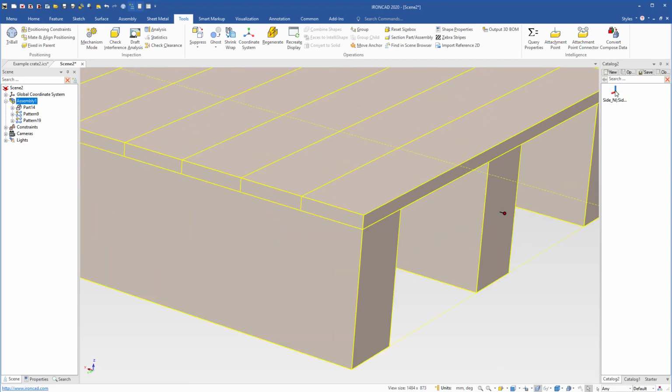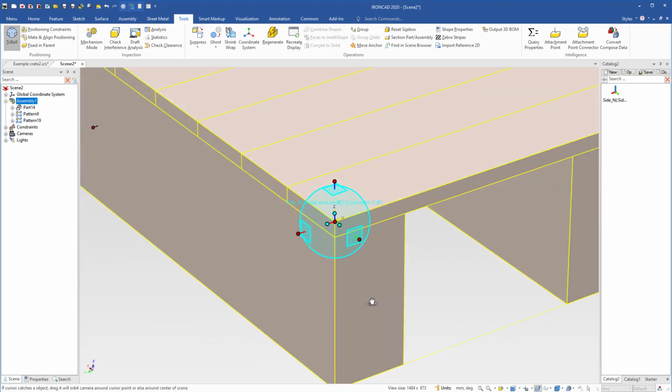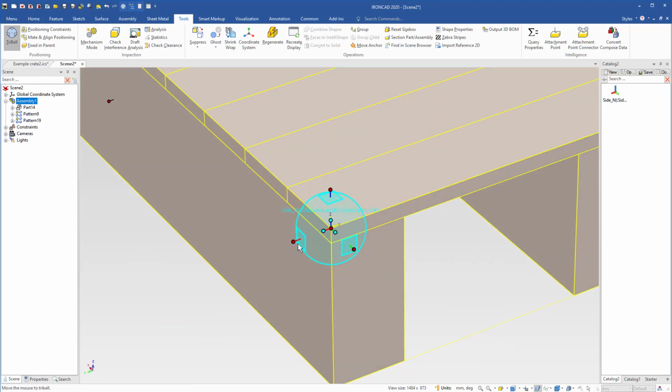So we'll select that assembly, drag and drop it onto here, and again we can select that attachment point, turn our tri-ball on, move it up to this point. Again, let's move it vertically, and we're going to turn it the X so it's pointing in this case 90 degrees. Now in this case we actually have a board that has a thickness inside of this, so we actually need to move it in or offset it. That board thickness was 20 if we recall when we built that, so it's going to move it in 20 inside of there. Okay, now this attachment is slightly different, so let's go ahead and edit this name and behaviors.